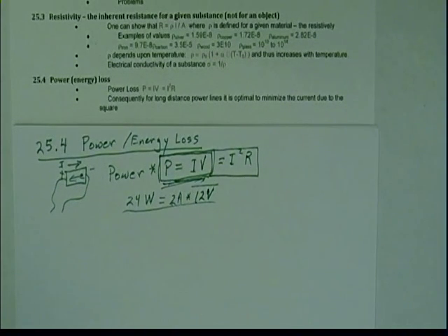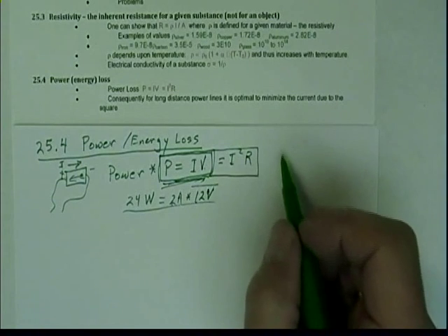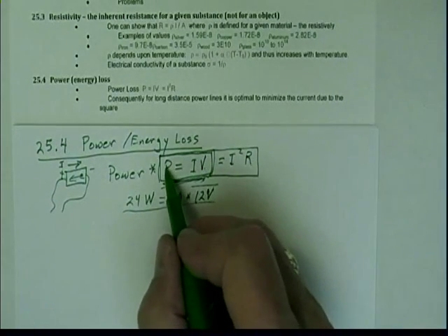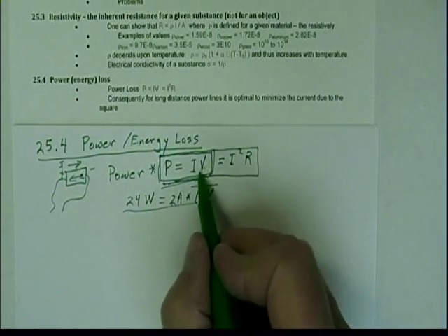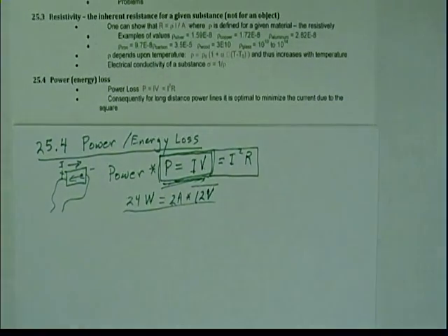I might mention in ordinary households, you would say, what are the trade-offs between using high voltage or high current? You could say, well, for a given power, one thing I could do is I could have very, very high voltage and very, very small currents. Why would I want small currents? Well, you want small currents because I don't want losses in there.